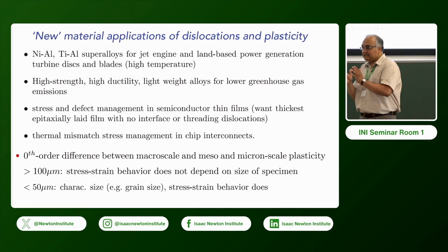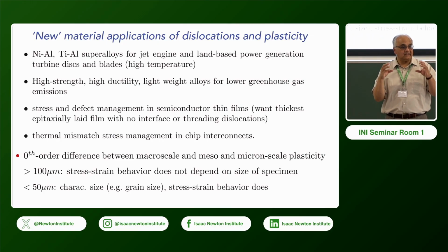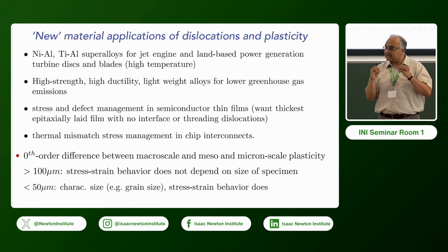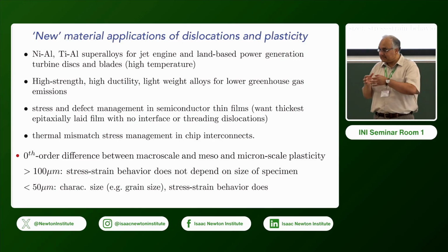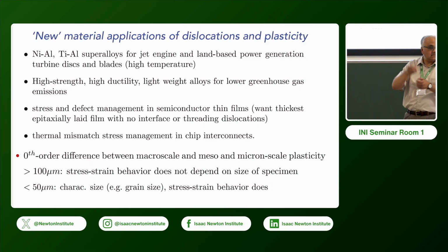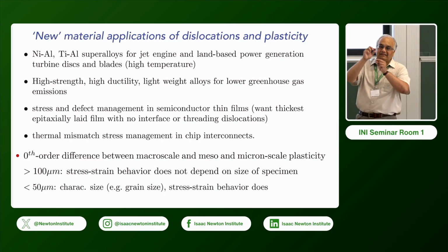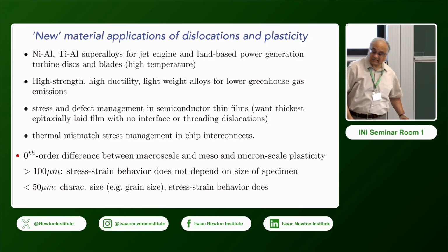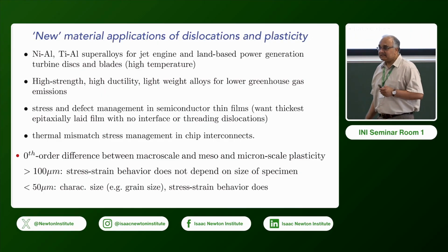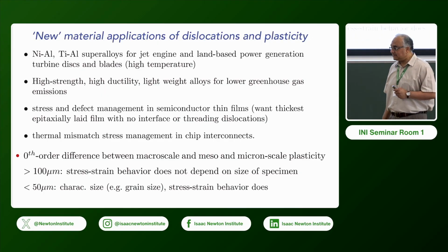So for the same material, force displacement curves will vary depending on the geometry of the specimen. But stress-strain curves, macroscopically, are not dependent on the geometry. This is why you reduce it to stress, force per unit area, times length over deformed length, the displacement over the original length. This is not dependent on size and geometry. So it's a material characteristic.